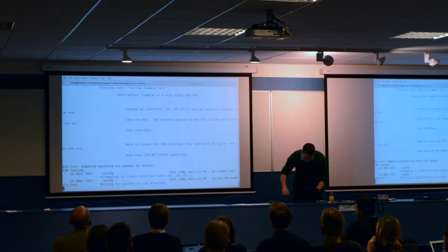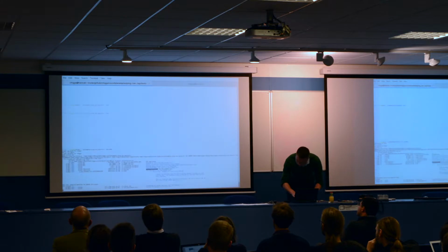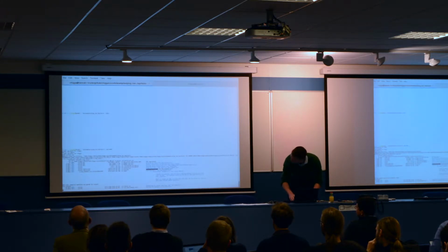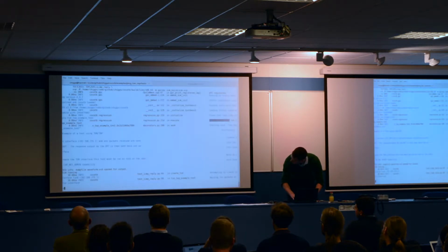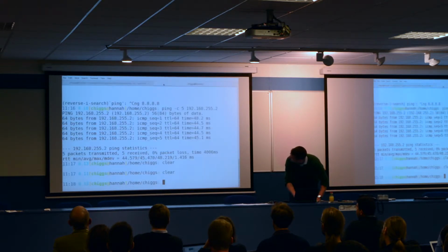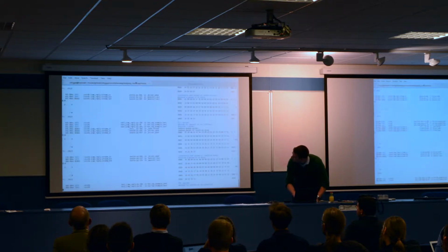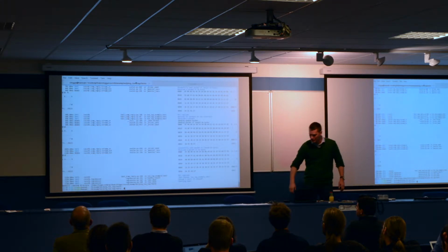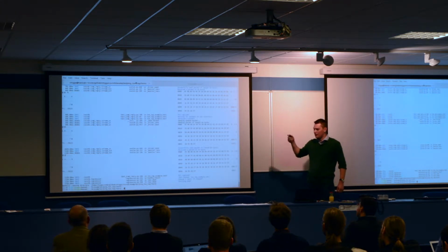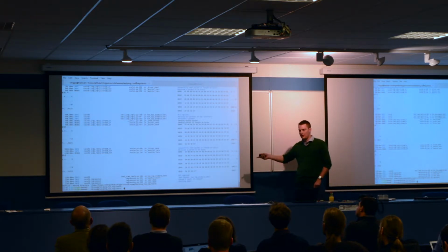Okay. So this is now running Icarus, and we've created a virtual interface in our simulation. Apologies for the size of that. But if we switch back to the next terminal, we can just ping our simulation, and we can see that we get responses from our sim. That's going back to ping. So in 10 minutes and 50 lines of code, we've created an environment where we can run unmodified Linux command line utilities and co-simulate them with our RTL.